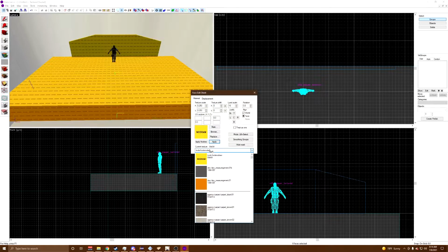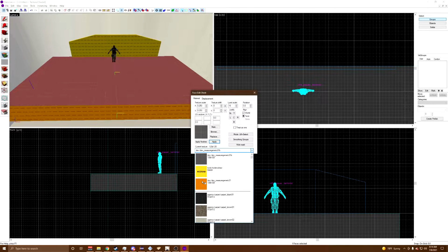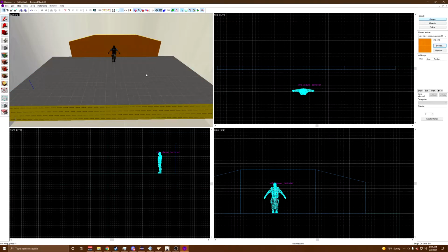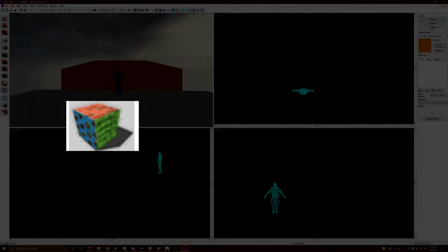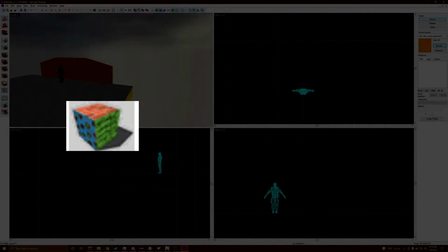I'm just going to take the time here to texture our walls and floors with our dev textures. And you can see how it instantly helps distinguish the walls and the floors from each other. You can change the textures of individual faces by selecting the texture application tool on the left side of your screen.